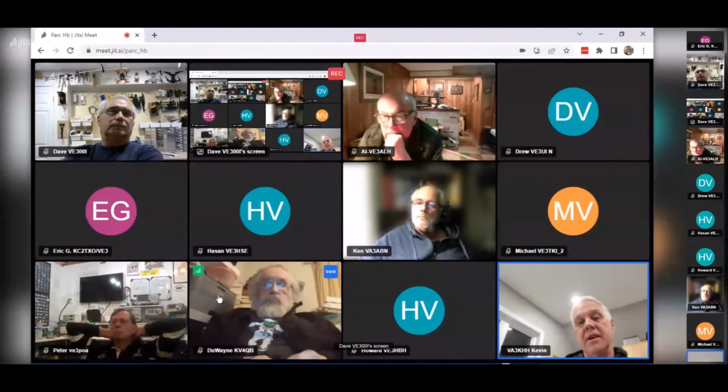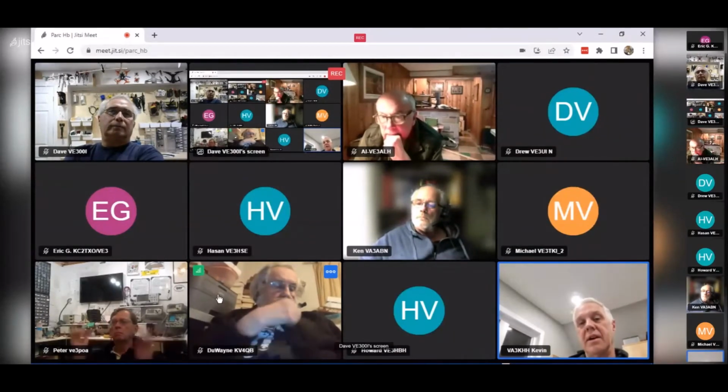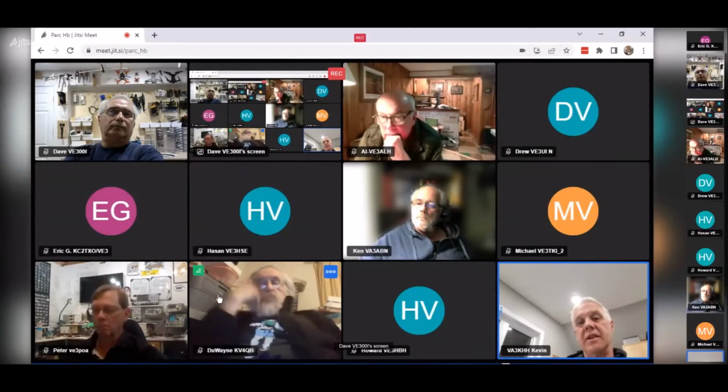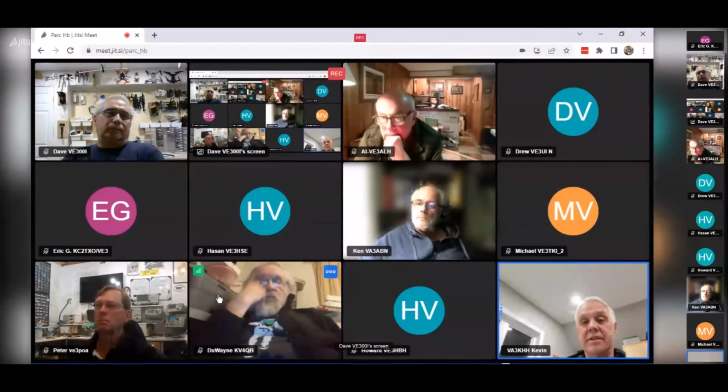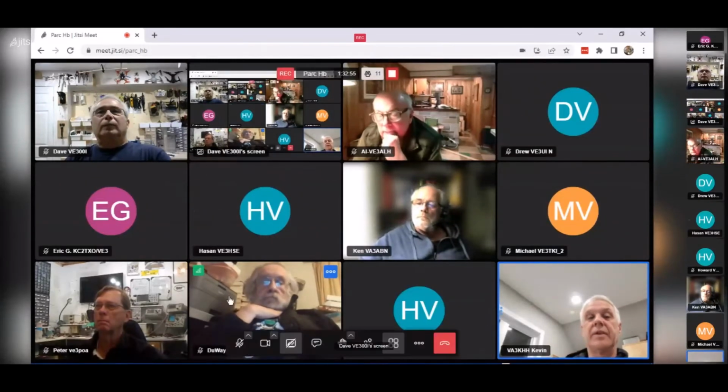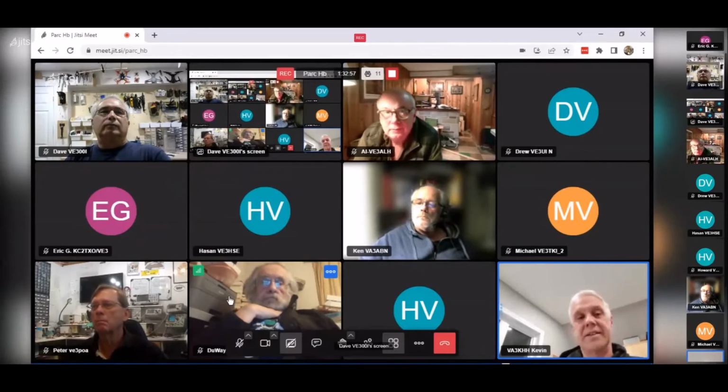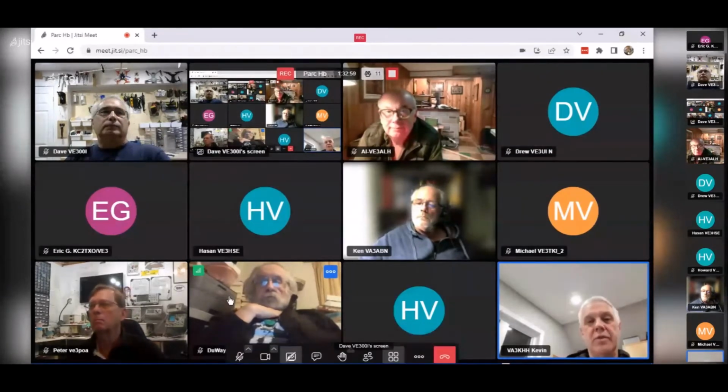And you're right, it's discrete steps on a stepper. But a servo can do pretty amazing position regulation as well. And there's a lot of reasons that you don't use steppers, especially in high inertia loads, because they don't like inertia. That's the other thing. Whereas servos can deal with it because they've got an internal torque loop. But anyway, it's getting into the nuances of control theory.